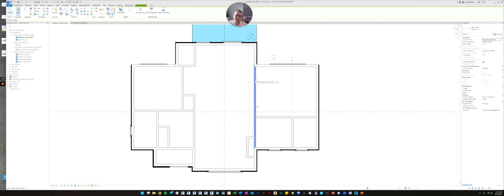And because it's a system family, the settings are kind of a little bit hidden. So you remember if you click on the wall, we can go up here and we can change the type of wall. You remember this drop down where you pick your wall type? We could change this 4-inch wall to a 6-inch wall if we wanted to, right? And you can see it changed thickness. We're going to change it back to a 4-inch wall. So you can change the wall type, and you can change where its top and bottom constraints are and its location line. We talked about all that, but how do you change its layers?